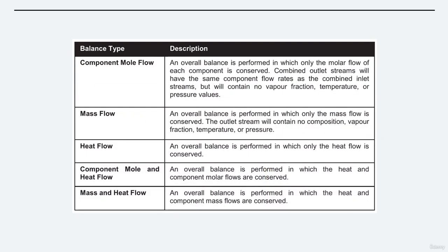The first balance type is component mole flow. That's an overall balance in which only the molar flow of each component is conserved. Combined outlet streams will have the same component flow rates as the combined inlet streams, but will contain no vapor fraction, temperature, or pressure values.